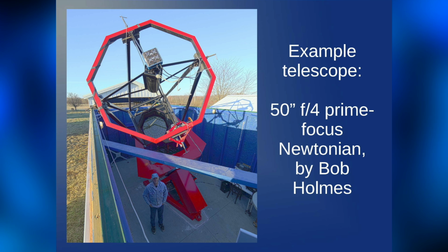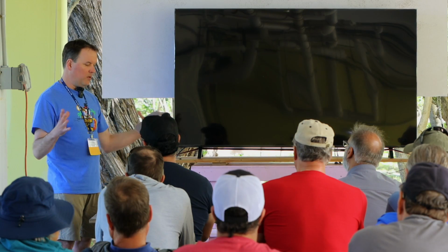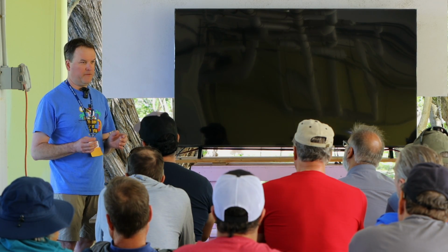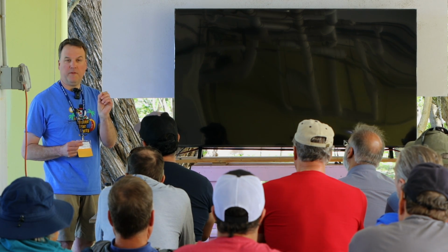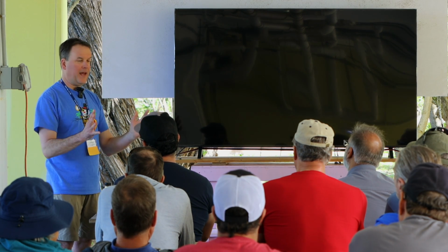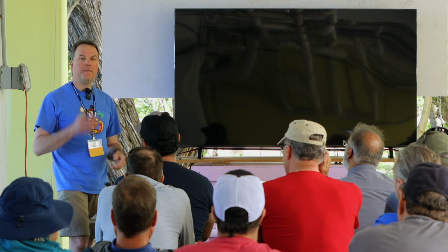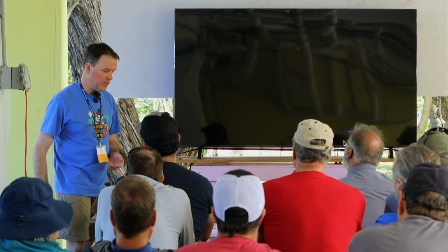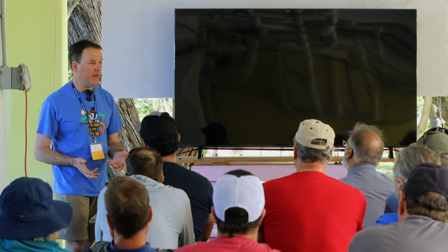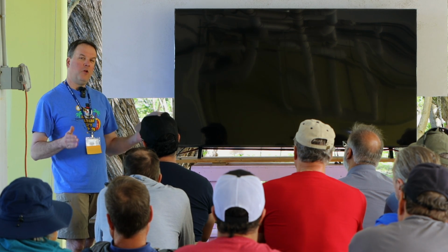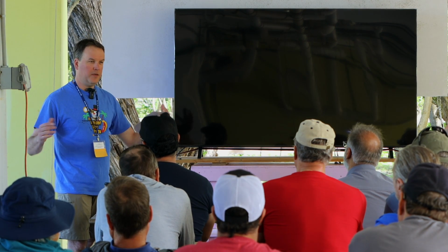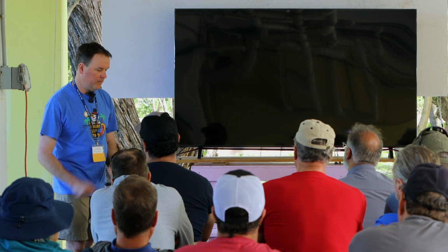In steel, when you have a 30-degree temperature drop Fahrenheit, the cell is going to shrink by about 9 thousandths of an inch. Okay, so you can actually see that with a feeler gauge over that temperature drop. The mirror is going to shrink by almost 3 thousandths of an inch, so the difference is about 6.5 thousandths again. So we want a little bit more than that, just in case the metal is going to cool quicker. So generally you want to say about 10 thousandths of an inch so that mirror is not pinched.